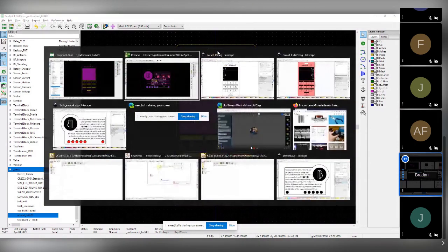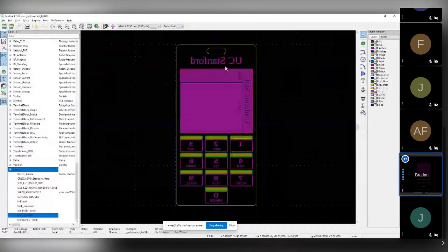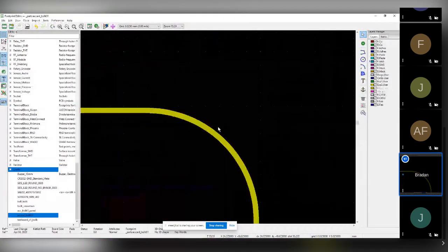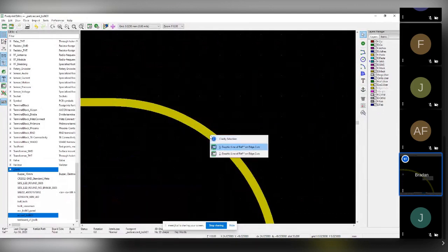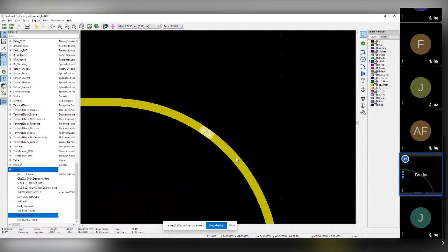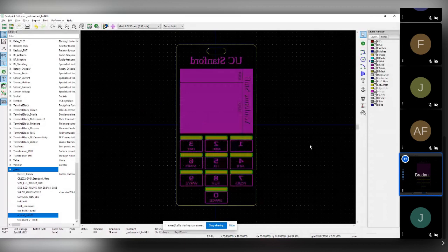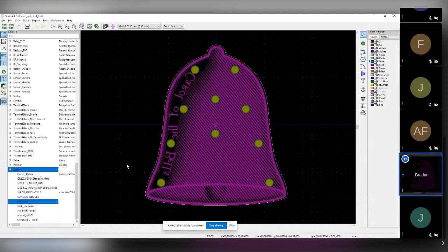But yes, it does actually go and create a big polyline for the whole thing. Matter of fact, if I were to go in here, you'll actually see there's a line segment, and it segments this whole thing, as opposed to trying to create primitives that KiCad recognizes. It just creates tiny little line segments out of everything. Which, by the way, is why you can imagine this footprint is huge, because these are all tiny little line segments.